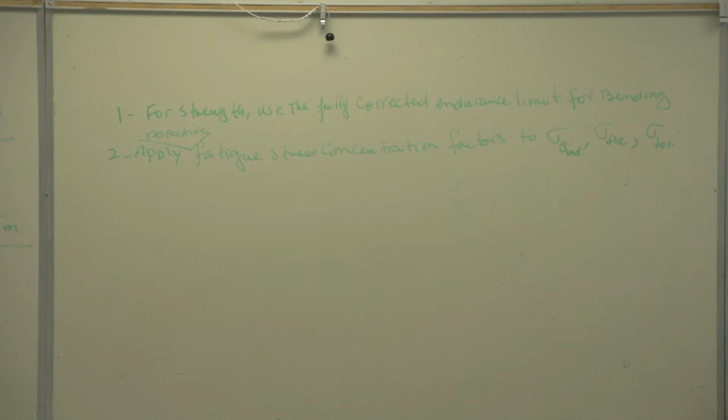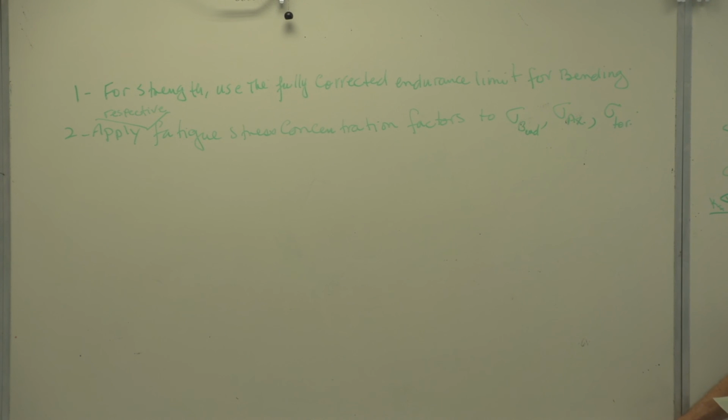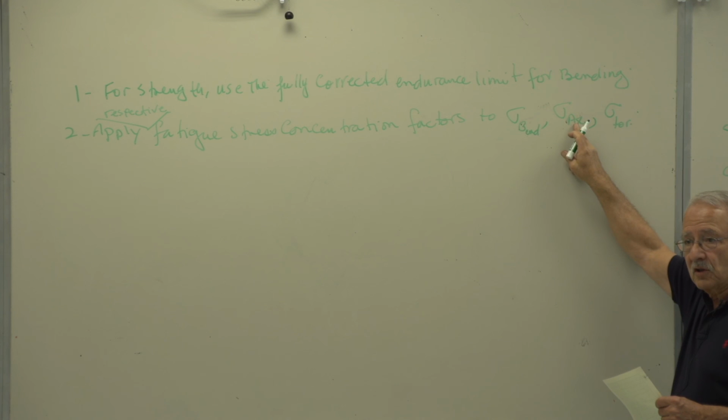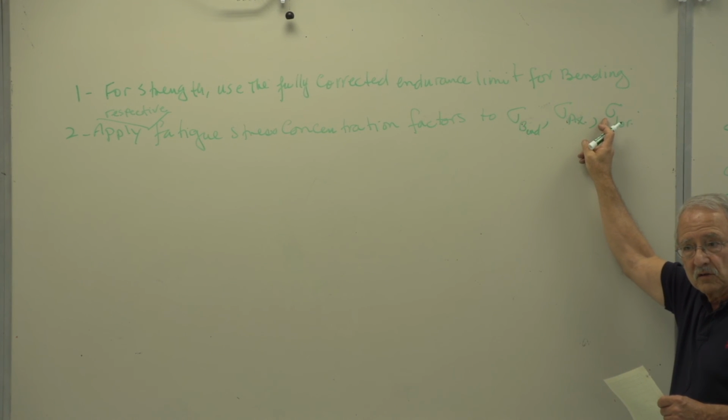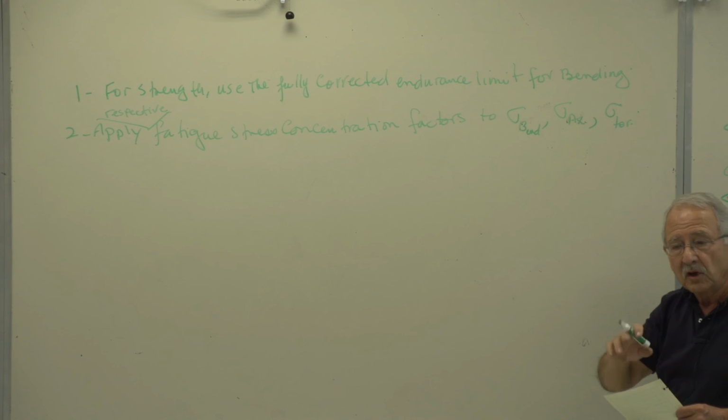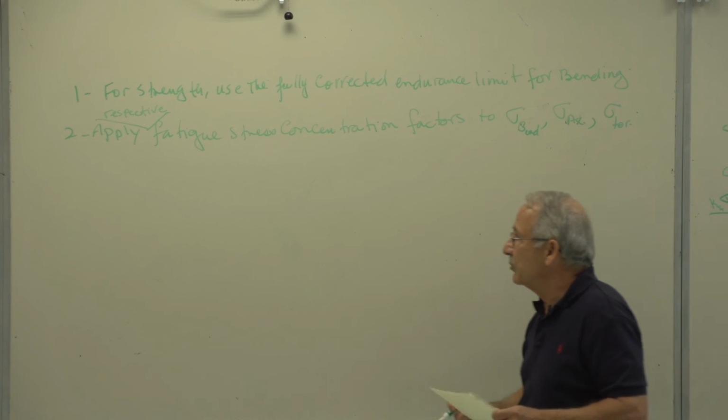Apply fatigue stress concentration factors to these. Respective means this has one stress concentration factor, that has a different stress concentration factor, that has a different stress concentration factor. Same discontinuity. I'll demonstrate this in an example problem next time.